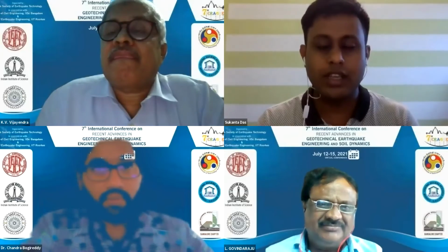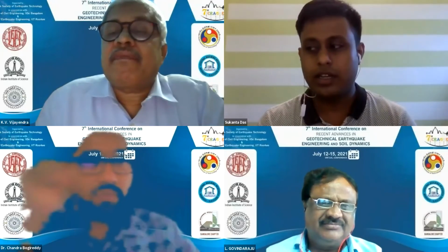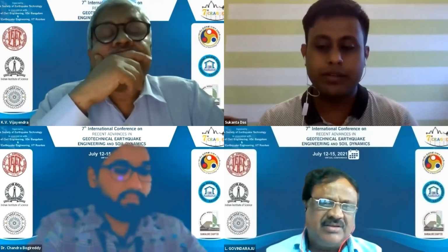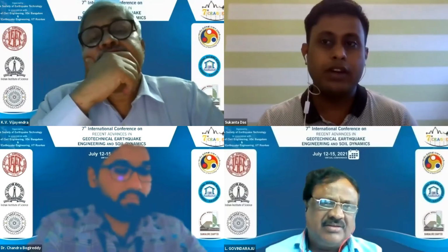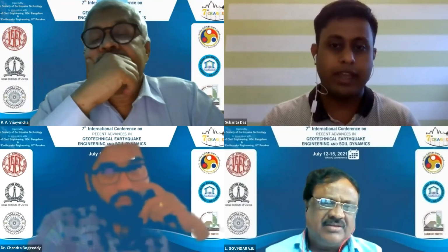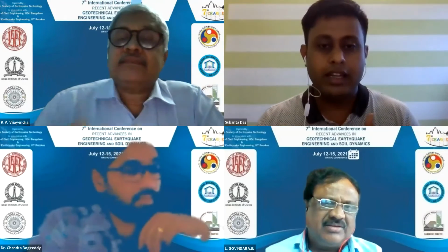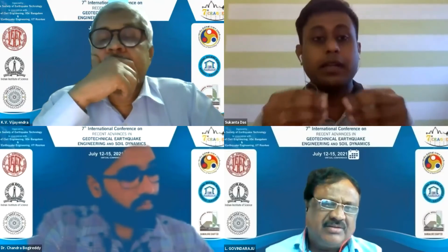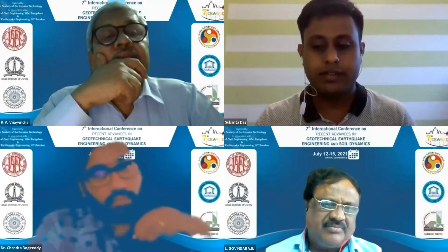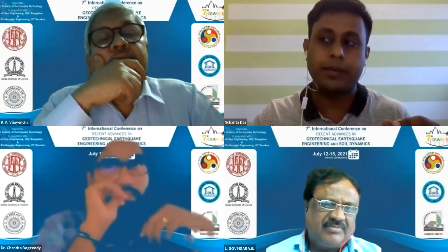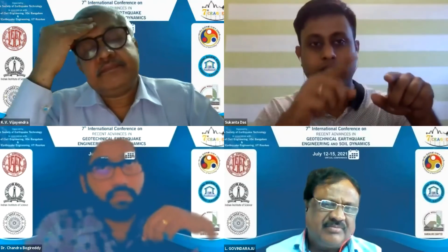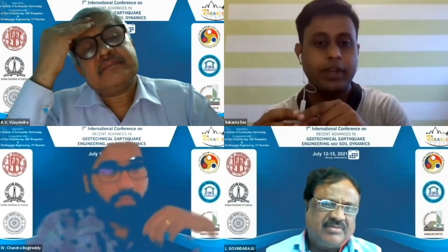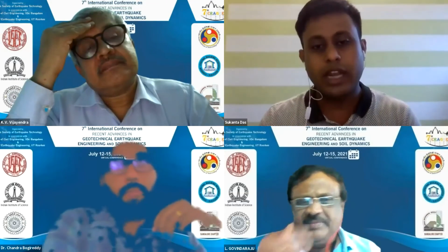Actually, sir, in my PhD work I have investigated this, why they have recommended it, but no literature has discussed these things. From our research, we find that beyond that frustum angle, which I shared earlier in the slide, the load dissipation, the pressure bulb generating beneath the foundation, should not cross that sloping surface. So approximately, after several experts' opinion, it was considered to be near about 30 degrees.